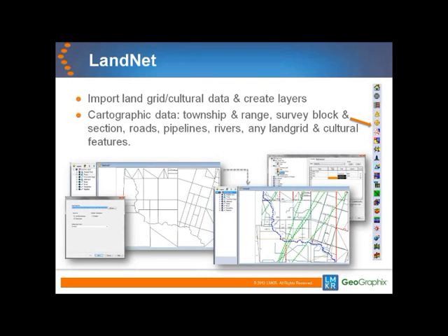The files can either be imported as display layer and can be saved as shapefile for display in GeoAtlas or export, or can be imported as land grid database, which can, as an example, be used to distinguish individual lease holdings in a lease map.